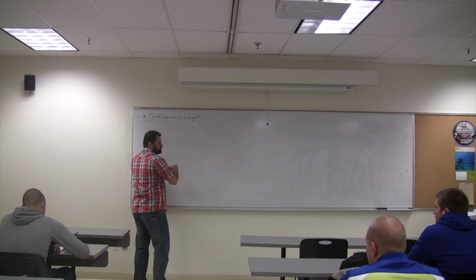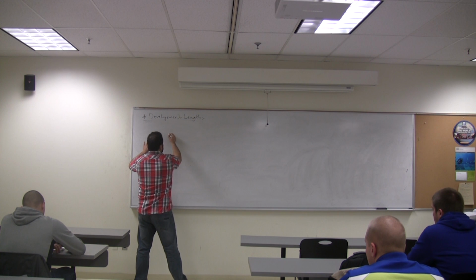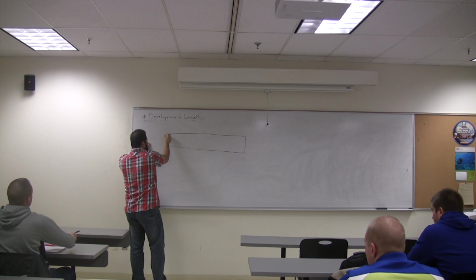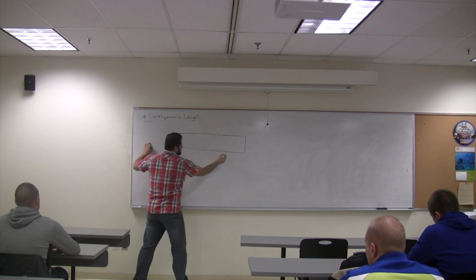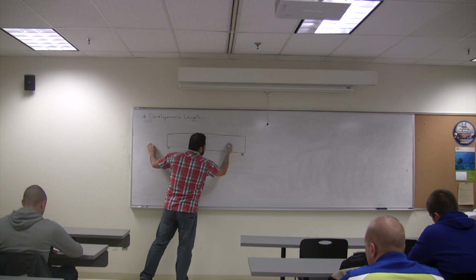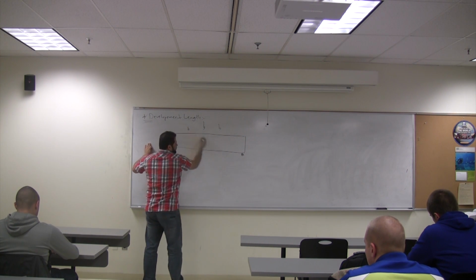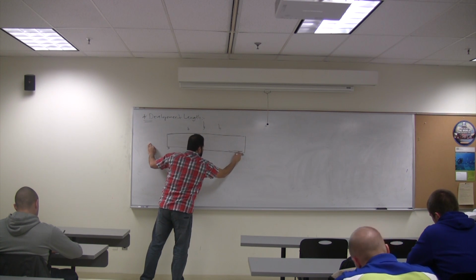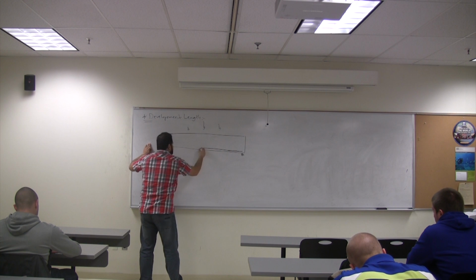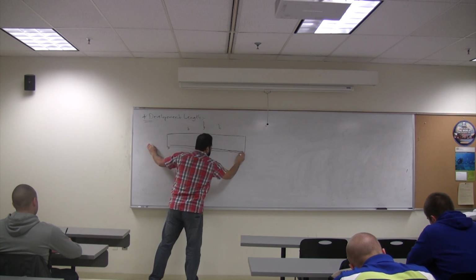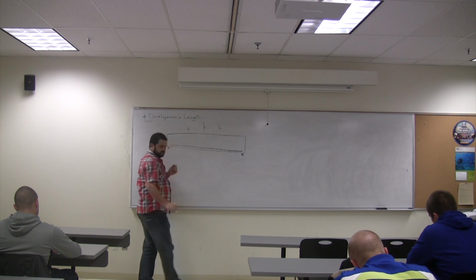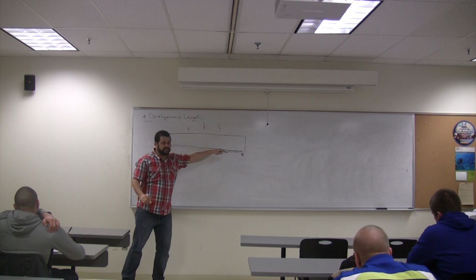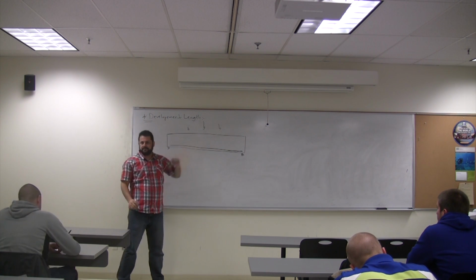If you have a beam like that, this will make it clear. If you have a beam like that, it's a simply supported beam. So we expect that the reinforcement to be where? At the bottom, right? This is the steel. At the bottom, you have 1 bar, 2 bars, 3 bars, 4 bars. But this is the level of the steel. Okay?